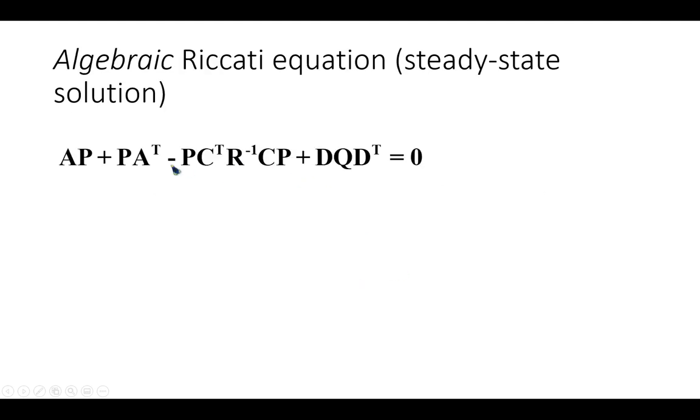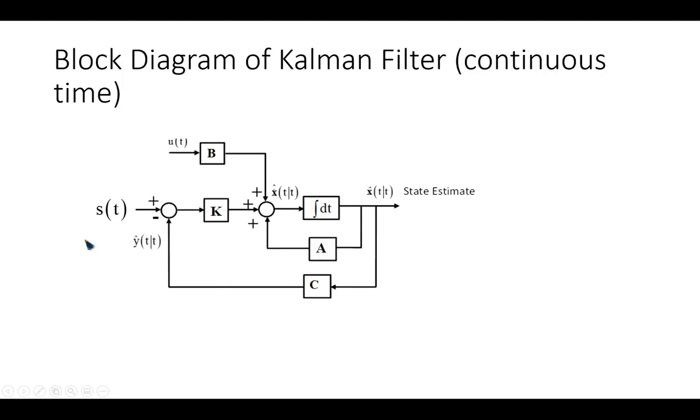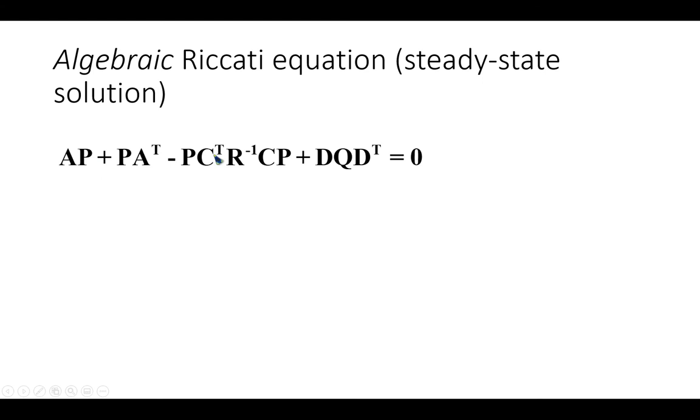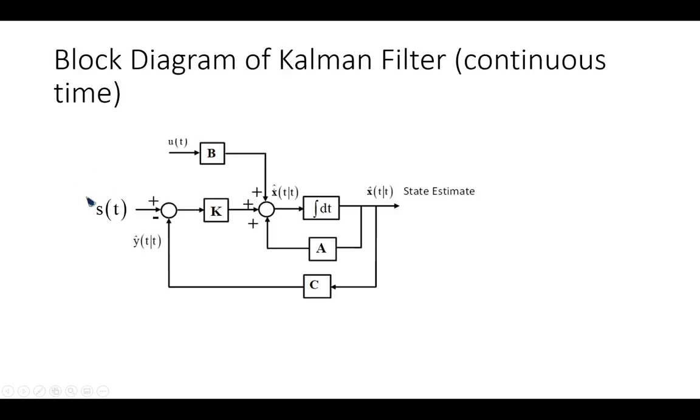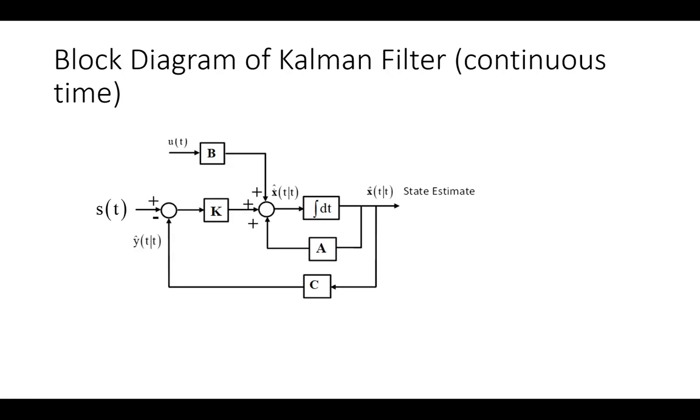Instead of solving for P dot, going back to here, if the rate of change P dot is 0, then you can solve what's called the algebraic Riccati equation, which I think is a little bit easier, but even for small problems, that can give you quite nasty nonlinear algebraic equations to solve. You can solve that for P if it's solvable, and then you can get K from that. But usually we find numerical solutions because it's really too hard to work out analytically, apart from very simple problems.